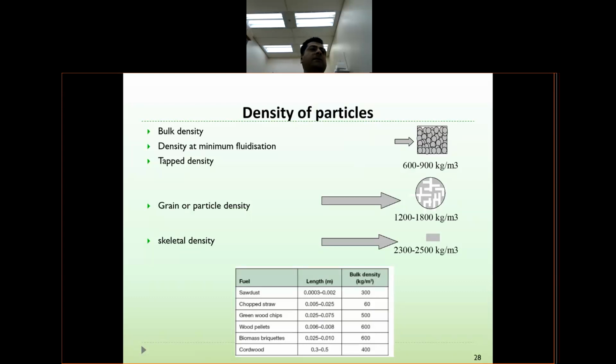And another reason is, for example in terms of biomass, by special grinding, you are changing the crystal structure of cellulose, and there are some other reasons. But the main reason for grinding is to make the handling and transportation easy, and to improve the contact between biomass and chemical reactants in conversion unit operations.